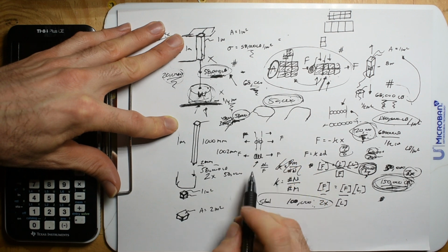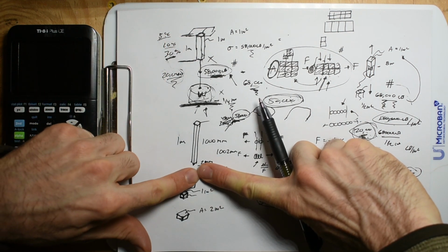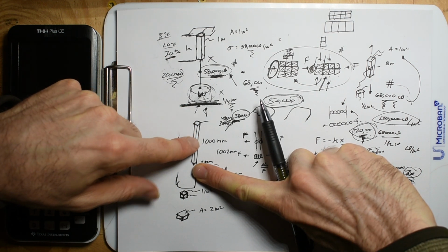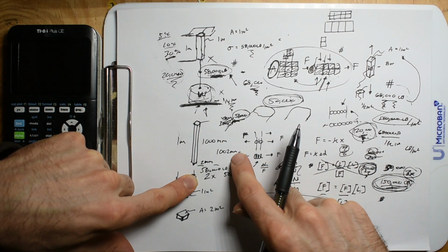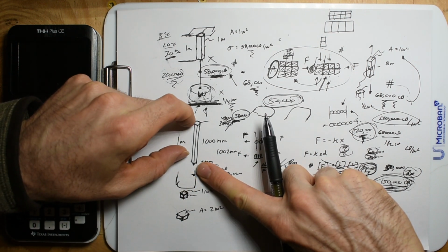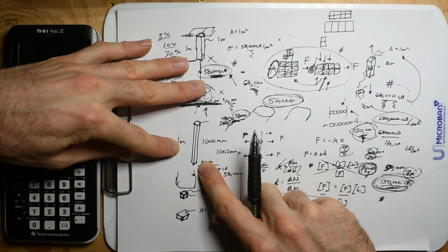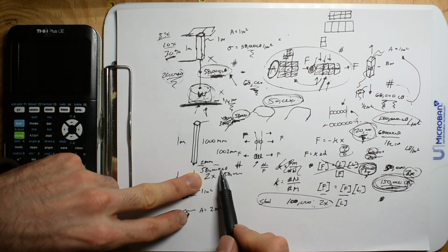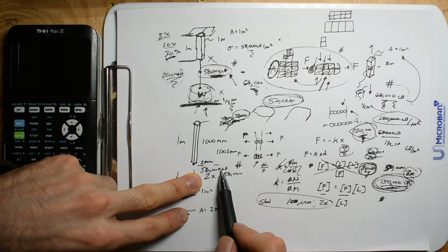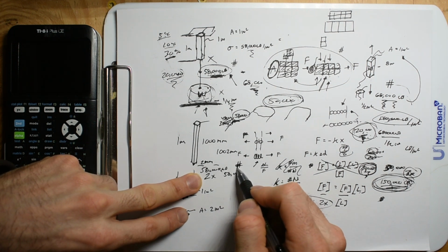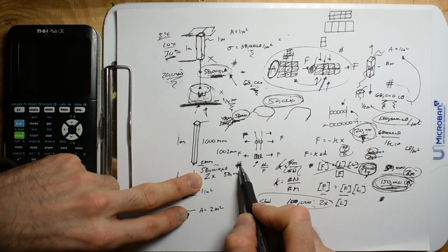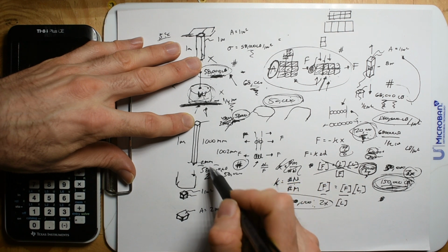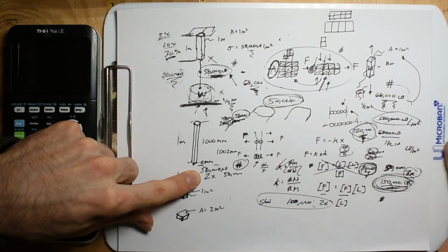It is now going to be 1,002 millimeters. And then I'm going to take that 58,000 pound weight off, and this bar is going to go back to 1 meter, 1,000 millimeters. I can put that load back on, 1,002 millimeters. Take the load away, it goes back to 1,000. Cool. So that's amazing that you can have a full strength, basically that yield strength, and when you back it off, it just goes to the same exact shape. So you can put basically the max, and this is very close to the maximum strength of the steel anyway.